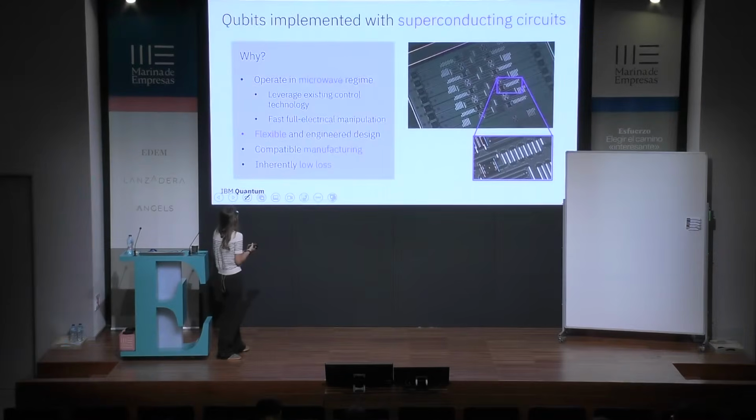Second, about the flexibility, this is a platform where we work with superconducting qubits, where you can write your Hamiltonian, translate it into an effective circuit model formed by some idealized capacitor, some idealized inductor, maybe a transmission line, and so on. And then you can just design that, put two pieces of metal with a certain capacitance, an inductor with certain inductance, and it actually behaves practically the same as what you simulated. So it's a very clean system to work with in that you can design a Hamiltonian and build it, and it will be what you wanted. So this helps a lot building something that works.